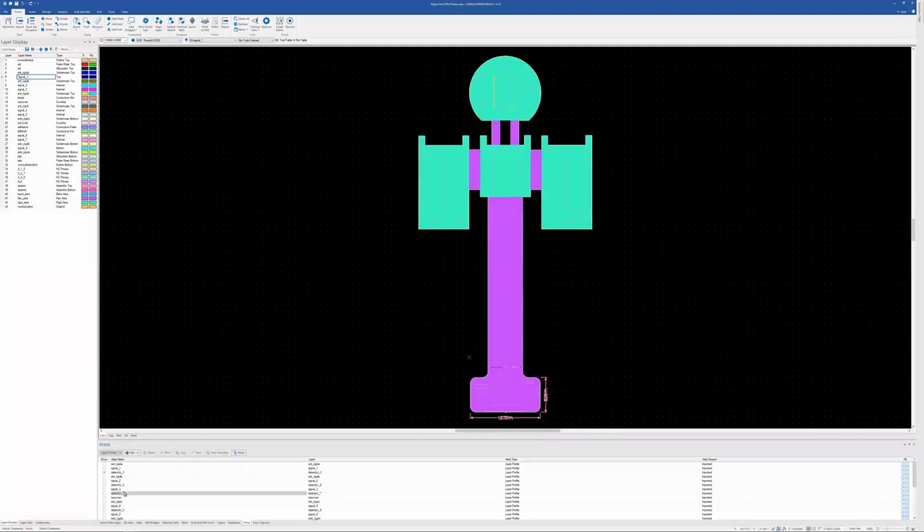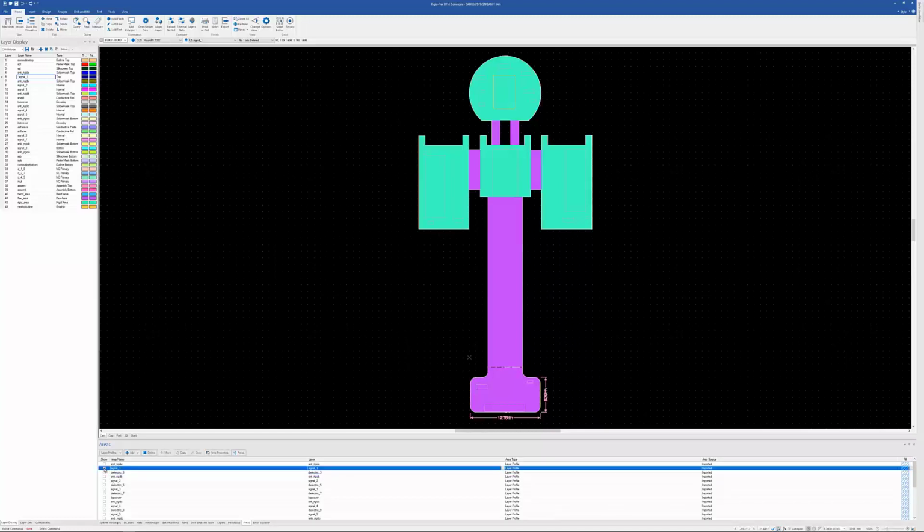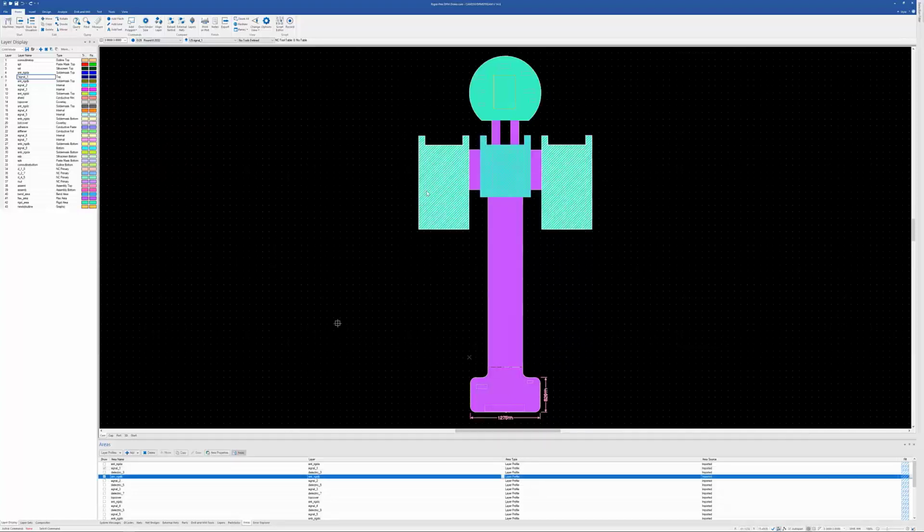Each layer might have its own profile, so that you're showing that area. In this case, what I call the chest area here, of our little stick man. And that is our rigid A area. Our rigid B area is over on the sides here. So these correspond to different stack-ups, and they are different portions of the board.